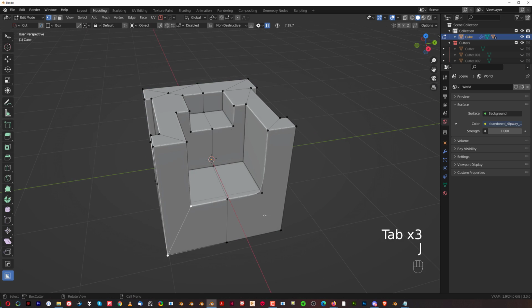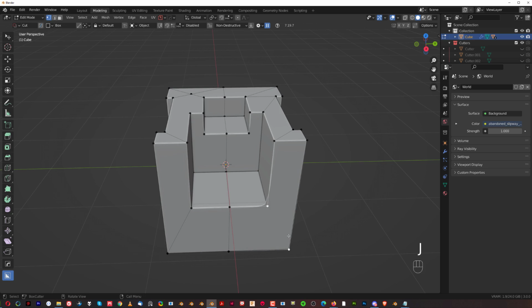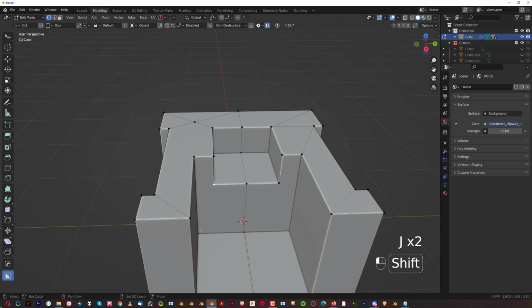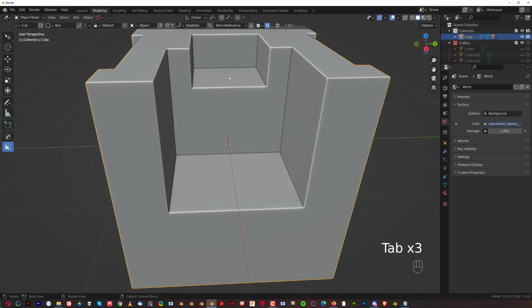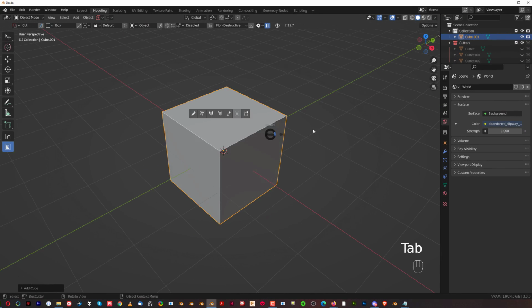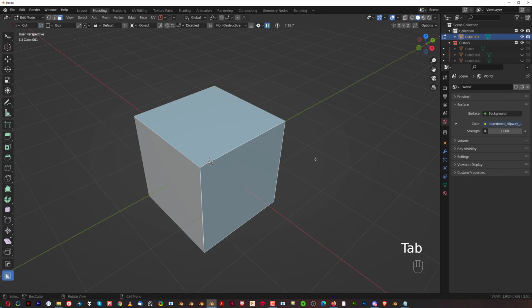Still need some stuff in here, some stuff in here. Probably connect these, and connect these, and there you go, guys. Subdivided mesh in seconds. Really awesome tool that I use a lot is Shift Curve Extract.